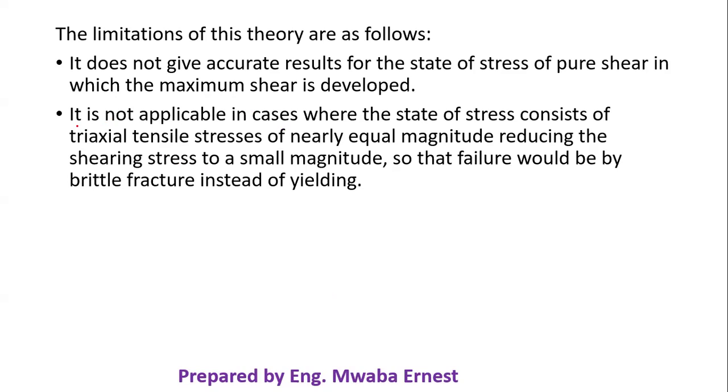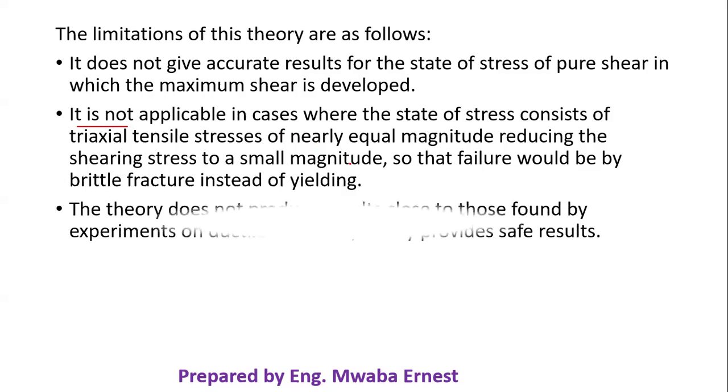you are not going to use this for a case where the stress consists of triaxial tensile stresses, where they are nearly equal in magnitude, reducing the shear stress to a small magnitude. So here, the failure may end up being determined by other means. So we're saying for such a case, this may not be used.